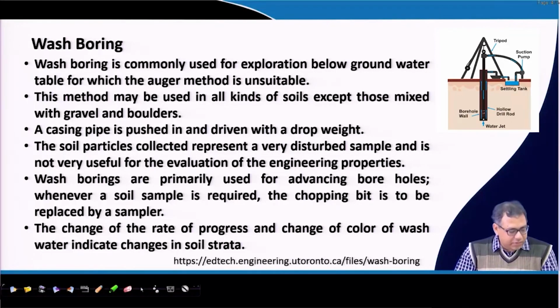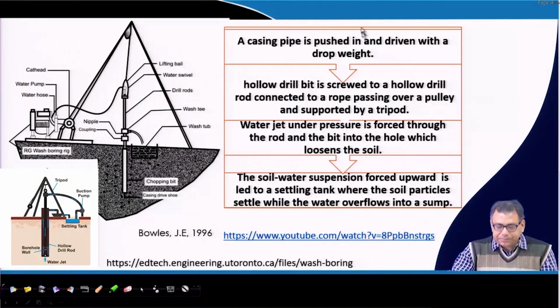Now I will discuss again the steps by which we can perform this boring technique. The casing pipe is pushed and driven into the soil by a drop weight. Then a hollow drill bit is screwed to a hollow drill rod inside the casing.